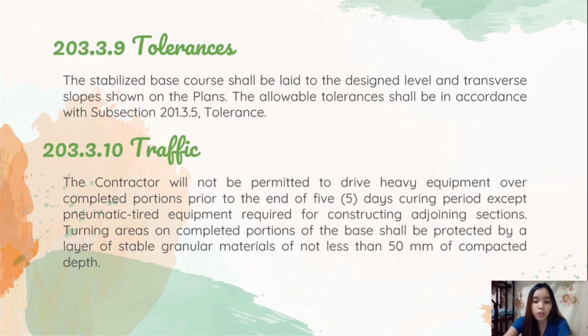So the contractor will not be permitted to drive heavy equipment over completed portions prior to the end of the 5 days curing period, except pneumatic tired equipment required for constructing adjoining sections. So turning areas and completed portions of the base shall be protected by a layer of stable granular materials of not less than 50 mm of compacted depth.